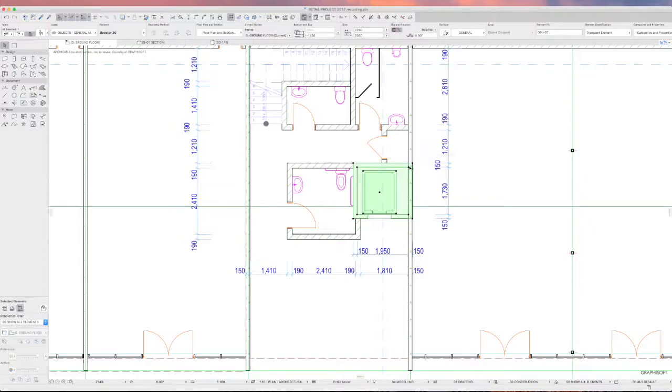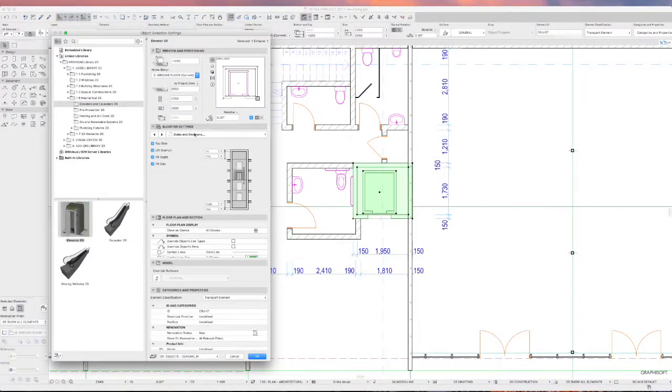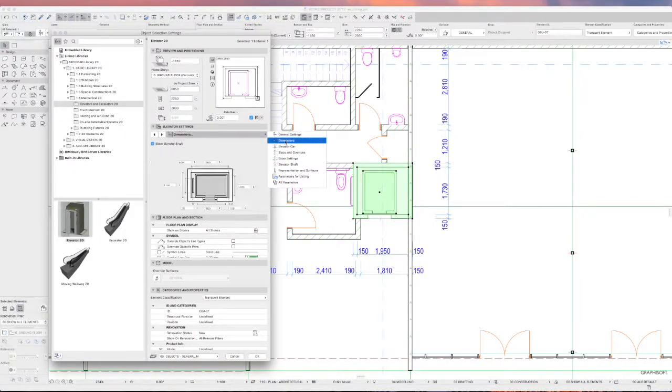The problem is that what we'd want to use is concrete tilt-up panels for the lift shaft. So it's put those in for us and it allowed us to dimension them back in the model here at 150. So that was in dimensions, I think. So that's why I've got 150 millimeters for the elevator shaft. But it only allows you to do it all the way around. It doesn't allow you to have different wall thicknesses on different sides of the elevator shaft.